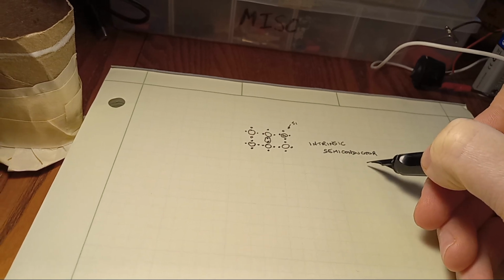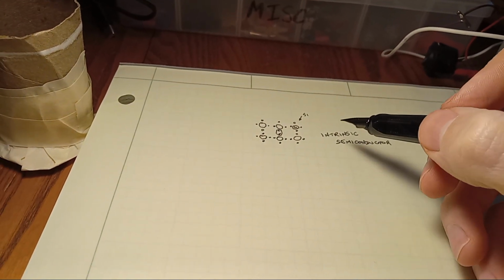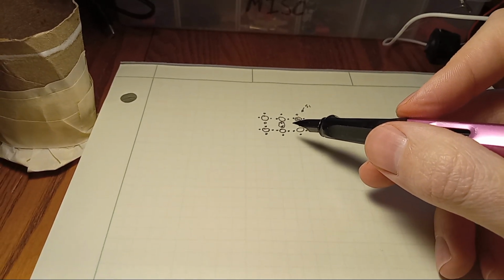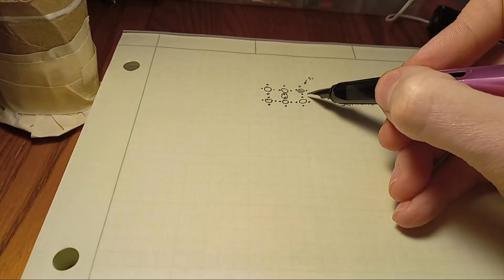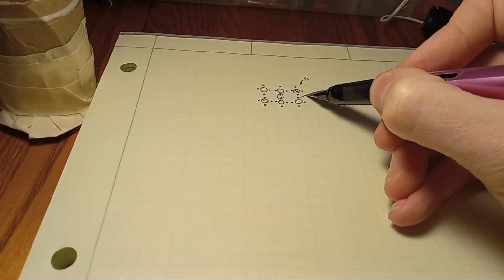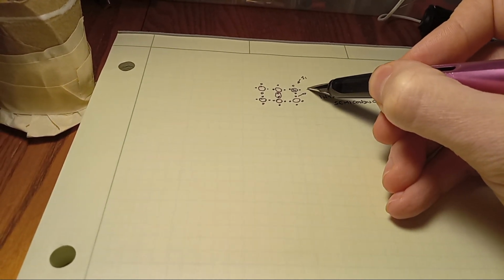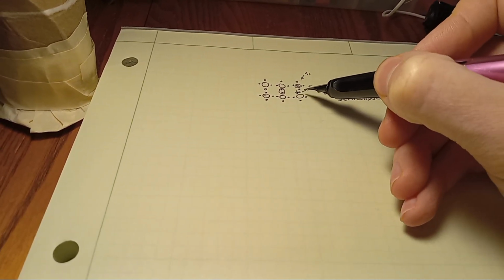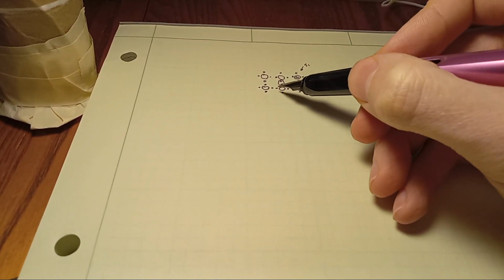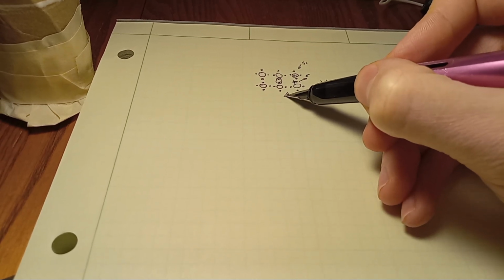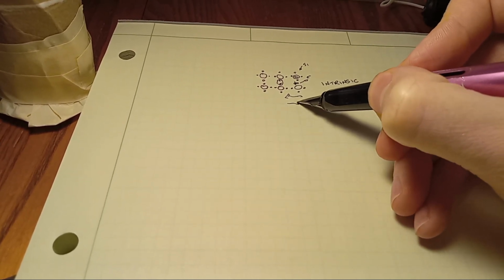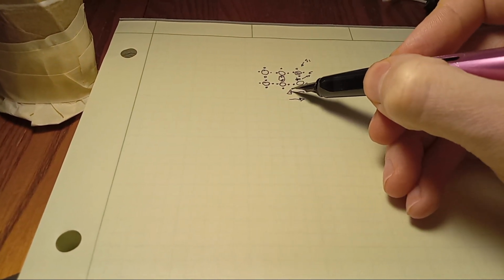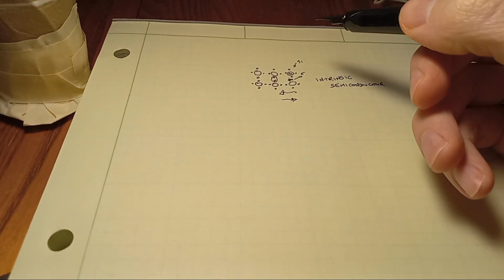At room temperature, it is a poor conductor, but if you heat it up, then it will be capable of conducting a higher current. And this is because heat will jostle these electrons free from their bonds, and so you'll end up with loose electrons and gaps where the electrons would be. Now, the loose electrons, of course, flow from minus to plus, and the gaps will flow from plus to minus. That said, completely pure semiconductors are not usually used for any practical purpose.